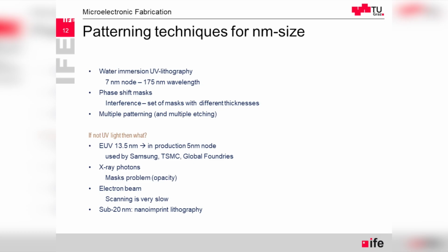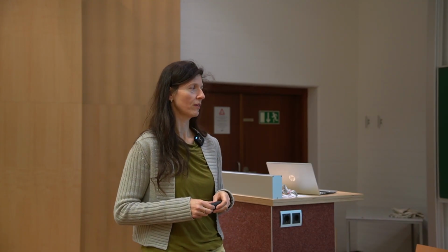Electron beam can also be used for patterning. However, it's similar to photolithography by nature. Here it's even worse, it's not illumination of the whole area, but really scanning a spot of electrons. Imagine doing that through the whole wafer, it's really very time consuming.